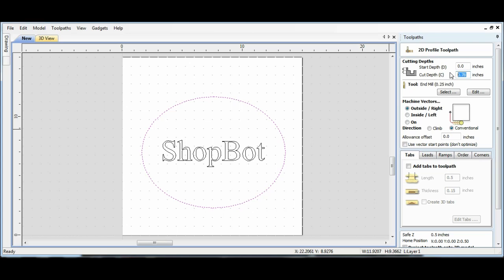So I'm going to do, since I know my piece of wood is almost exactly 0.5, 0.502. Nope, that's way too less. So just 0.512. You'll just get a feel for it. That's probably even a little too much. I'm just going to do 0.51. So I'm going to cut just a little bit past my material.